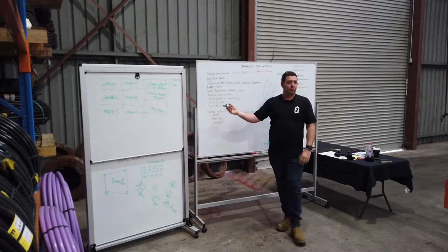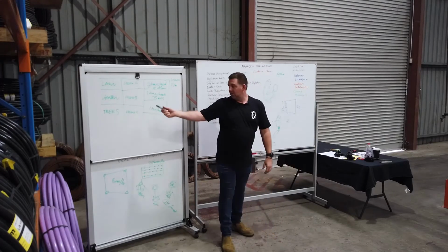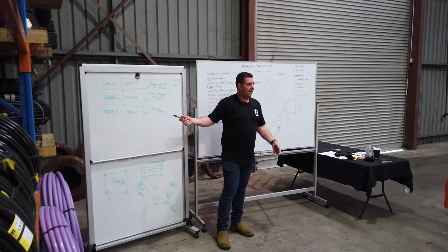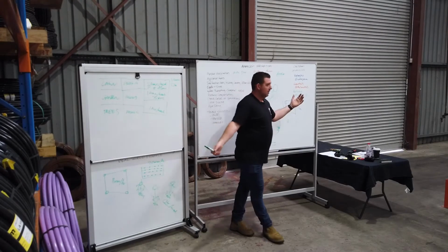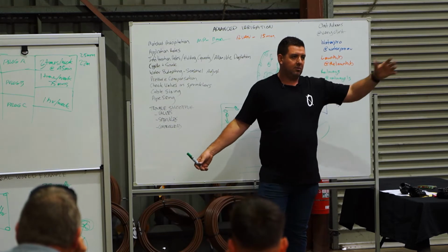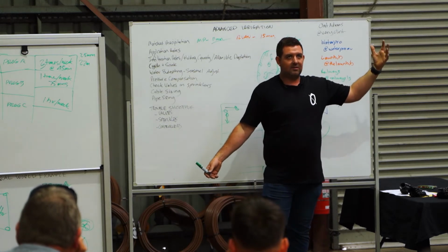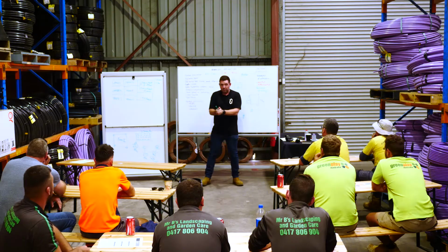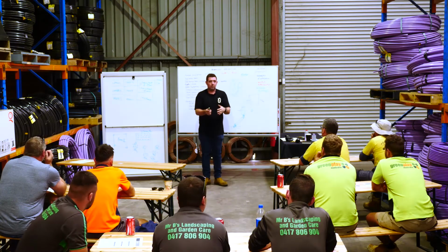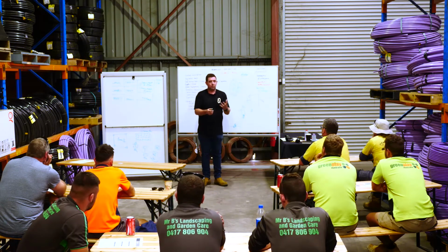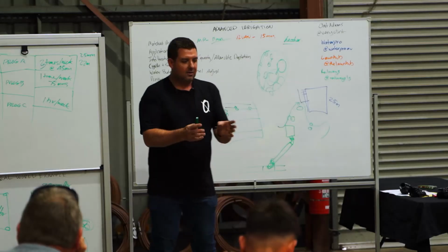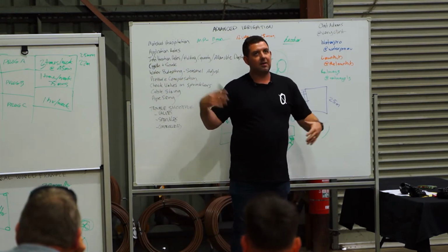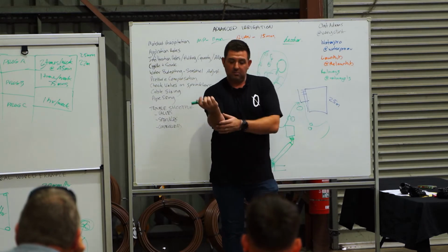Because on a golf course or in a public space or in a new subdivision, it's not the same as residentially, where you can just have the sprinkler come on for an hour every 3 days. They've got to water 10,000 square meters or whatever it is, or what's a golf course like, 6 hectares, I don't even know. They can't water when people are playing golf, so they can only water at night. They can't water at certain times of night if it's too cold, because then they're going to have issues with disease. So they have to work out the exact amount of minutes of water that they've got, and then work out when they can do that. So decoder systems are great for that.